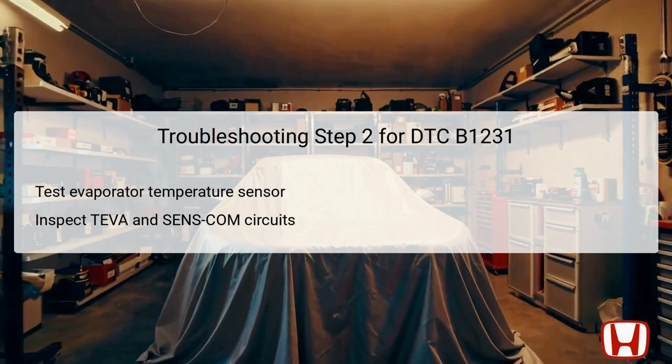Following the initial inspection, the next troubleshooting step focuses on testing the evaporator temperature sensor itself. This involves inspecting the TEVA signal circuit and the SENSCOM ground circuit. Disconnection of these circuits is essential for conducting a thorough examination, which ensures that readings are not influenced by additional electrical noise or shorts. By conducting open and short inspections on these wiring connections, technicians can confirm whether any breaks